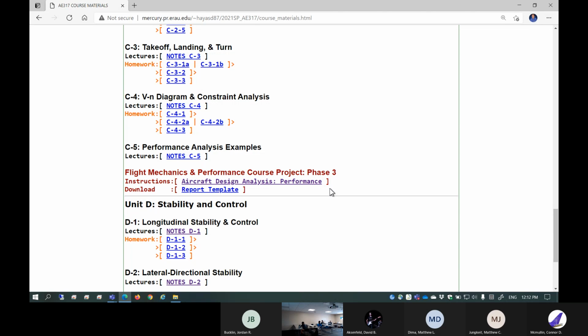First of all, you need to come up with a thrust curve or power curve or both. And then based off of that, you're going to compute the performance. The performance is going to be fairly set, and some teams need to add some more. Takeoff and landing is going to be more important for SAE, but other teams may not. Other teams may need range and endurance, power of gliding. There are lots of concentrated performance requirements to begin with. You need to show that your airplane design satisfies those things.